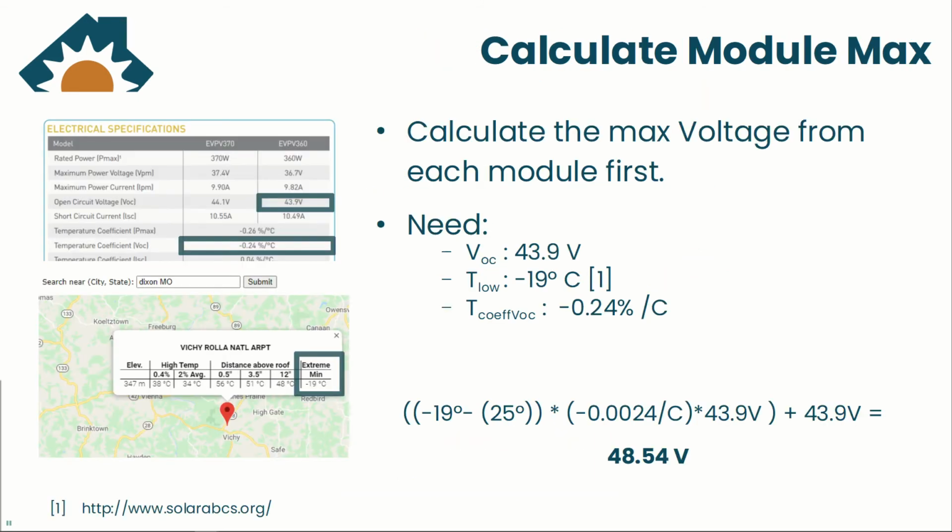All right, you guys ready? This is the part where we're going to start actually calculating this, and this can be kind of intense if you've never done it before, or maybe you don't feel mathematically inclined. Just follow me here, all right? We can get through this. We can do this. All right. First, let's calculate the maximum voltage for our area. This will be determined by the module and the coldest weather in your area.